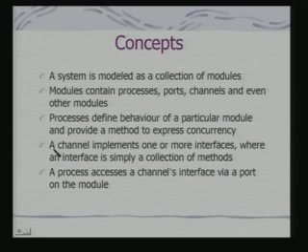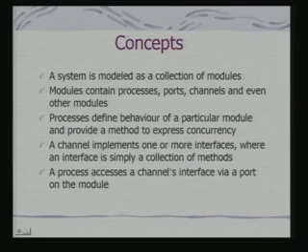A module can actually be a hardware module, and what we are talking about here is the encapsulation of the entire hardware module through an object oriented paradigm. A process accesses a channel's interface via a port on the module, okay? Because a process has to access the methods. If it is collaborating with other modules, it has to use those methods. So it accesses the channel's interface via a port on the module.